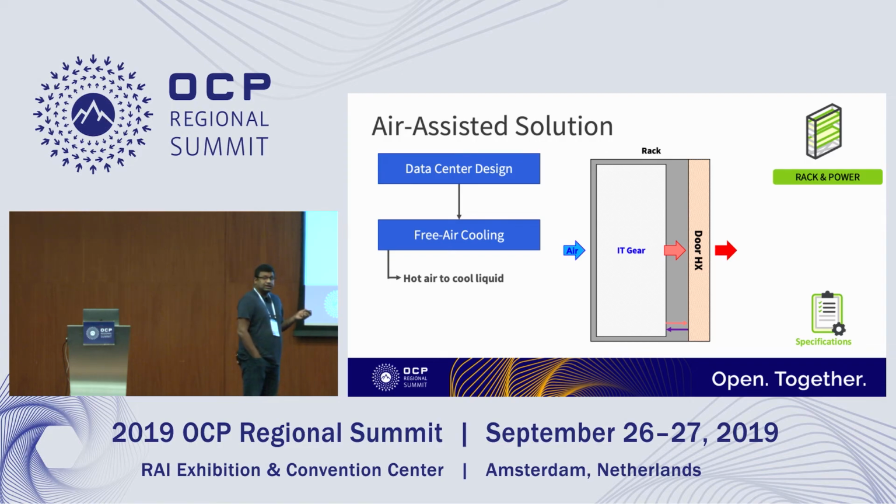And over here, you would need an in-rack CDU, because we're talking about a closed loop of coolant that's driven within the rack only. And at the end of the day, similar to an air-cooled solution, you have cold air coming in, hot air going out. All the heat transfer is to facility air only.